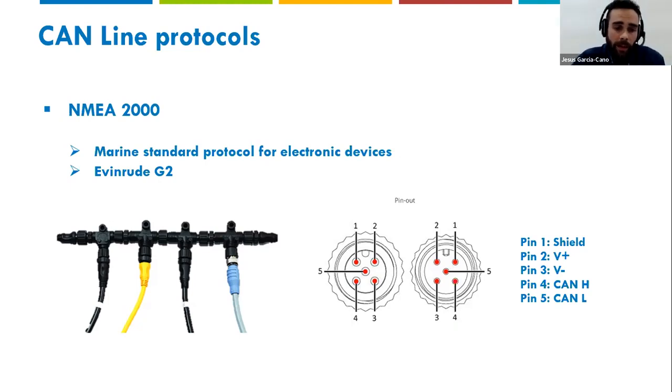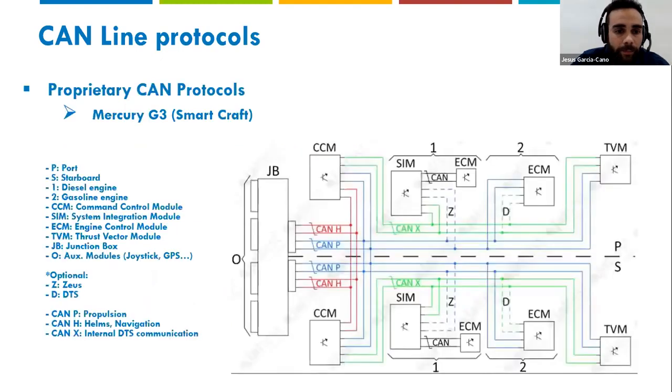Here we can see the structure very well. Here we have 4 T connectors with four different nodes, okay? For example, the first node will be the engine, then GPS, radio, sonar, and here we can see very well two terminal resistors. Okay, and for the last in that picture, we can see the NMEA 2000 connector, and this is the standard pinout. Okay, probably people know very well about this pinout.